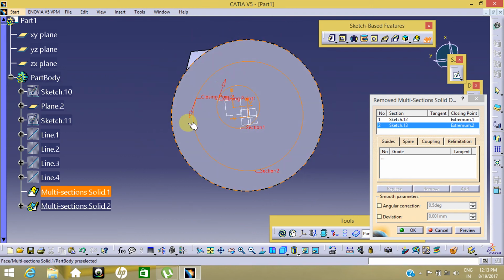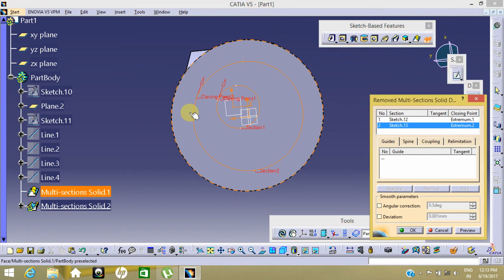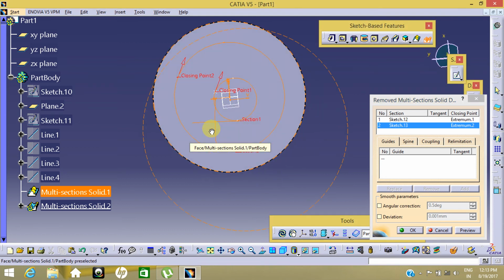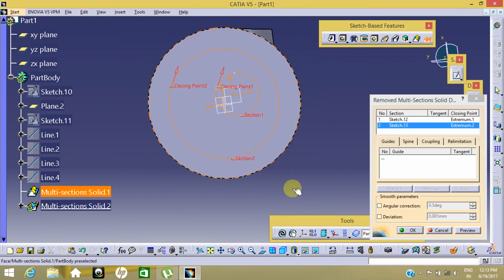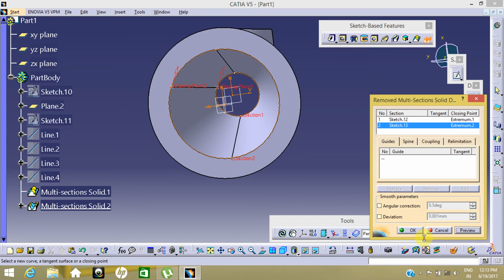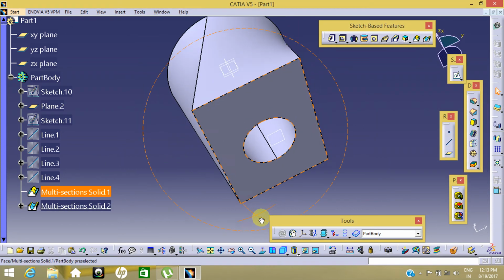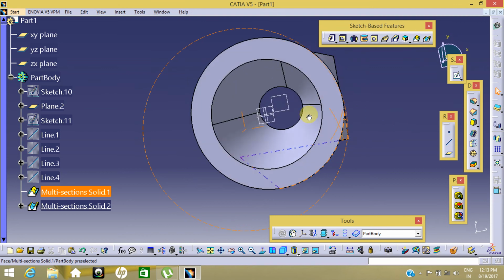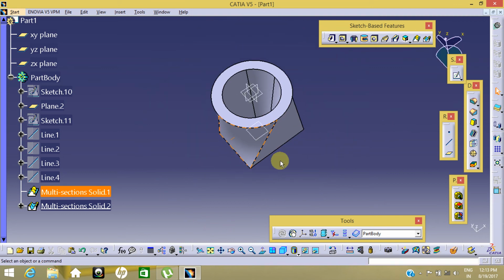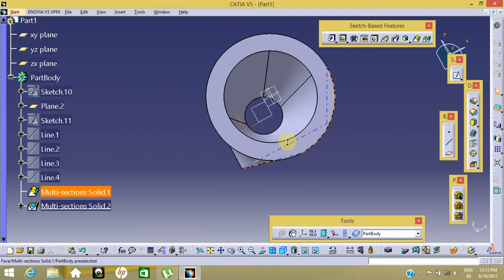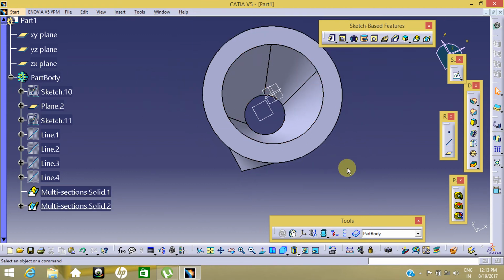Okay, so first of all we need to position the hole center. With the help of this command we can position it at the center, by providing the dimension from the surface. Like if it is 70, it might become the center. So make an exit, and it will be placed at the center point.